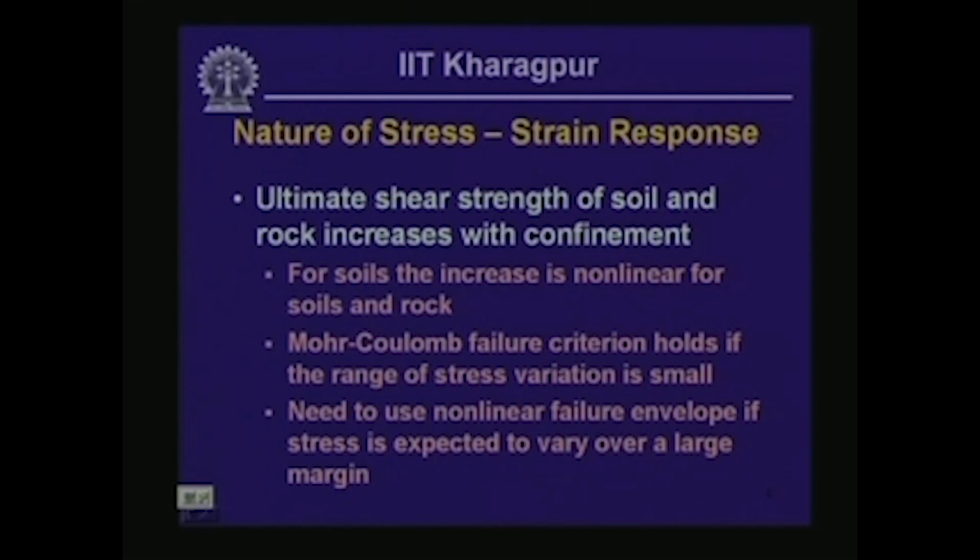That means, if you have got the same type of rock occurring at great depth underneath the ground surface, as well as at another level near the ground surface, an identical deposit of rock, then the strength behavior that the deeper element is going to exhibit is going to be much larger compared to the strength of the shallower element.